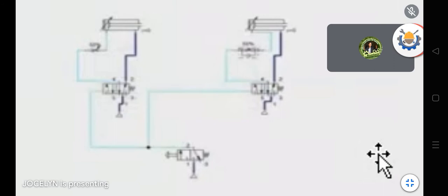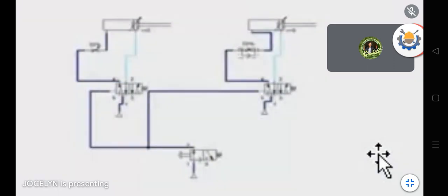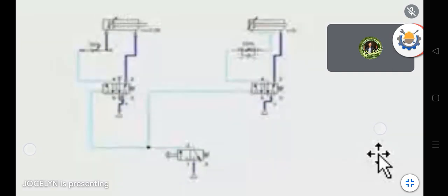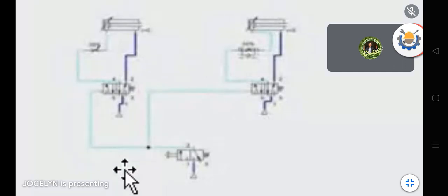So there, it is now on. So see, you can see the 50% actuation, it is slow. It is slow. But you see, okay? So you can see, guys, when we push the button to eject, both of them move together at 50%. That is because we set the throttle at 50%, and we also set the one-way flow control valve at 50%. So the air flow is slow at 50%. So they moved together, slow in extending.